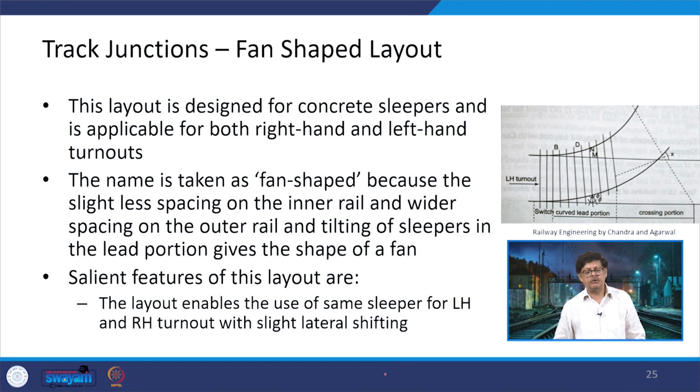Now, let us talk about the new designs which have come out. They are the fan shaped layout. This layout is designed for the concrete sleepers and is applicable for both right hand and left hand turnouts. The name is taken as fan shaped. Why is it being taken as fan shaped? Because of this type of arrangement which is being shown in the right hand side diagram, where you can see that it gives you a feeling of a fan.